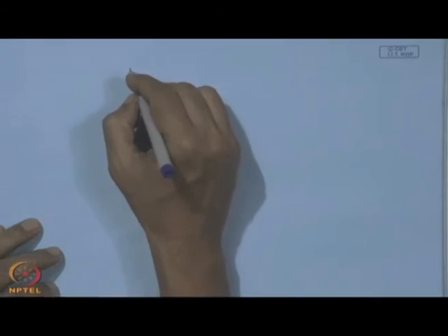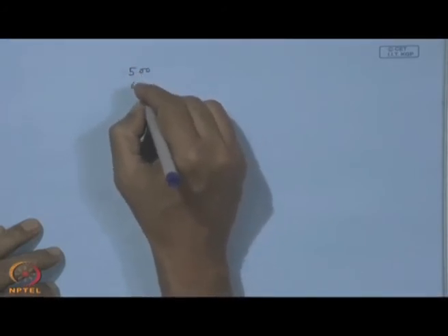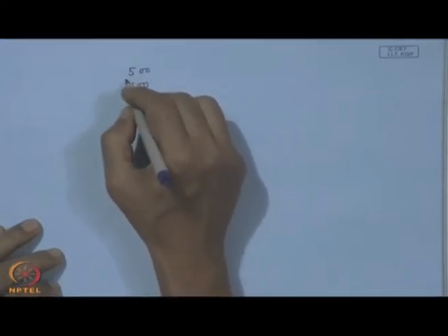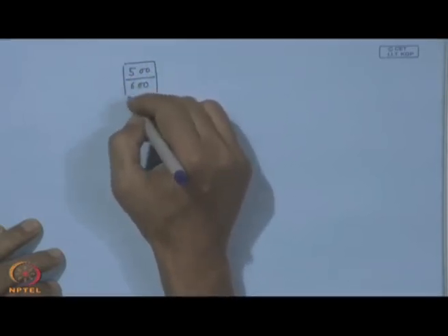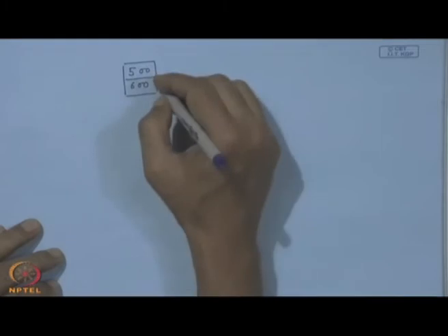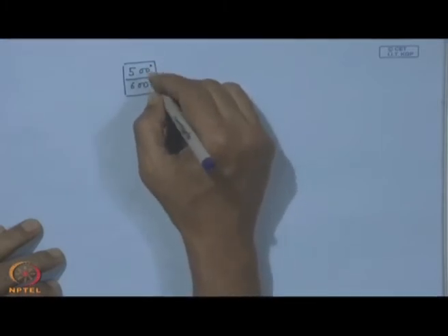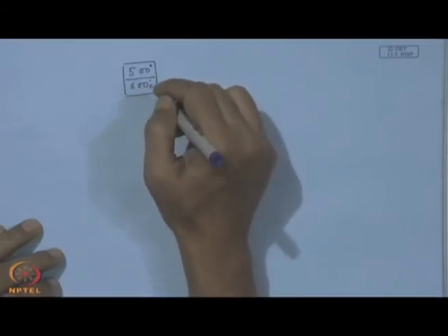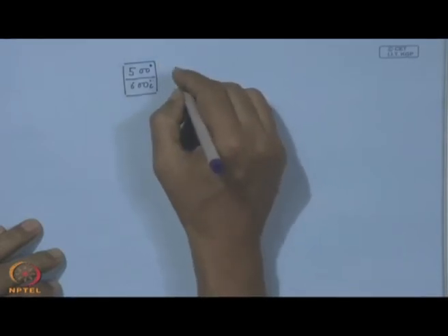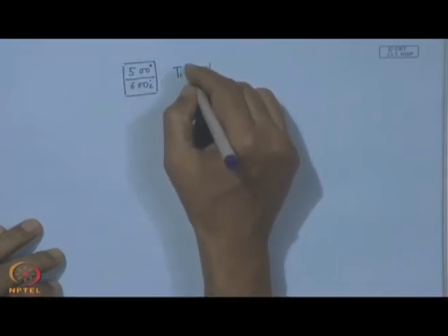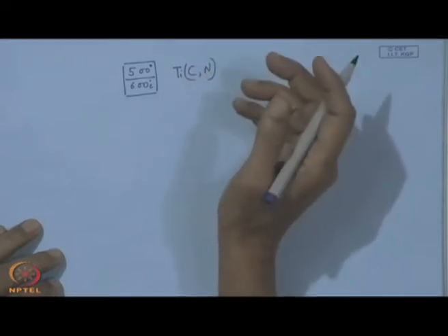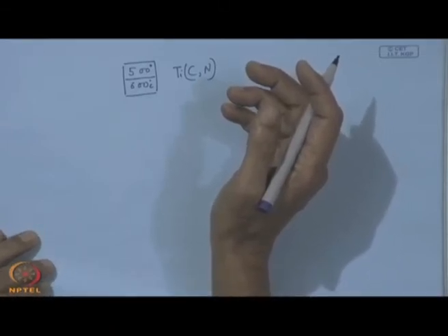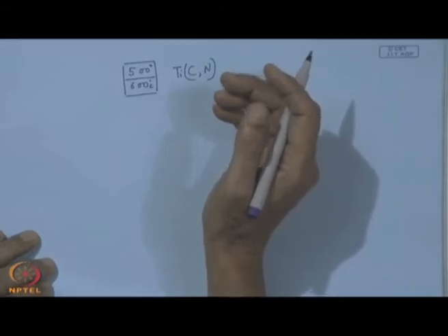That means, the zone say 500 to 600, even if it is lower than this, that will also be most welcome, but considering the limitation of this chemical reaction, one can fix a target of a range of 500 degree to 600 degree, not above that. And if we can conduct this CVD of titanium carbonitride by following another path, then that would be quite advantageous, and such CVD can have a widespread application.